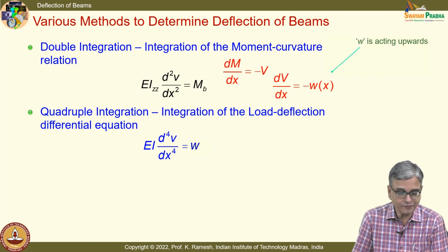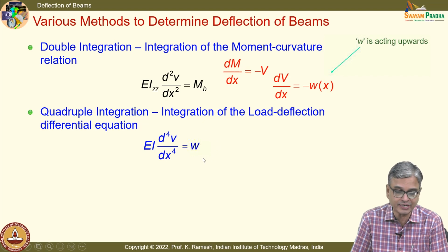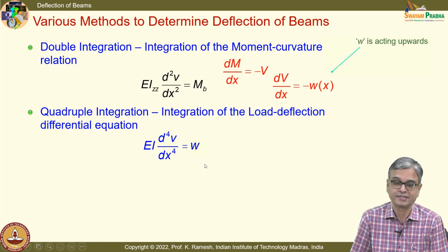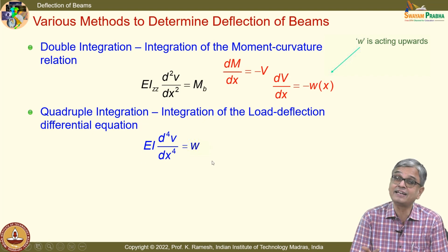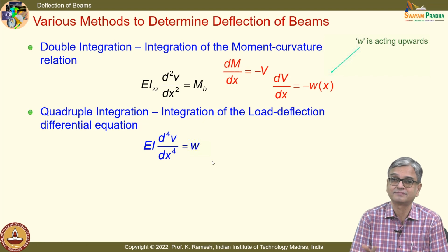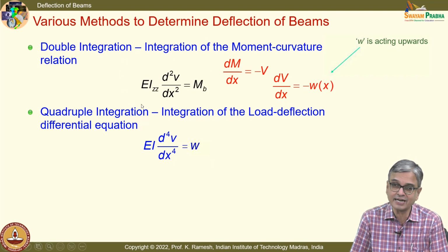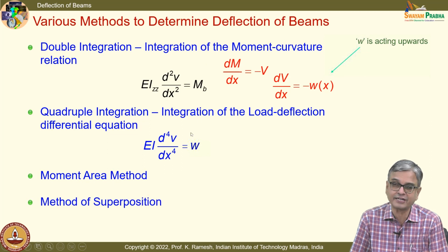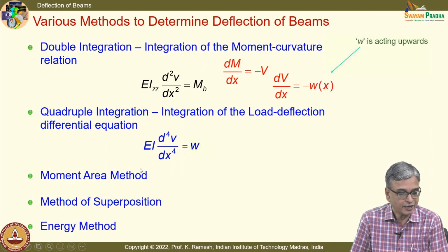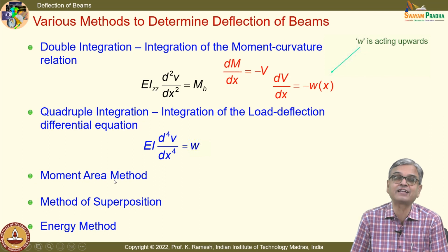On the other hand, if the load applied on the beam can be expressed as a continuous function of x, this is applicable for even statically indeterminate problems. So, this is primarily applicable for statically determinate problems. This is applicable for both statically determinate and indeterminate problems. And when you do this integration, you have done the integration mathematically. I can also do the integration graphically.